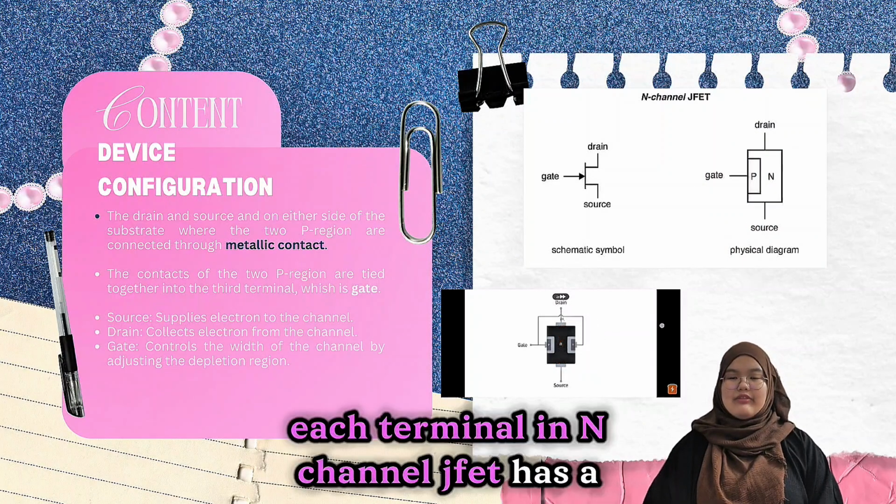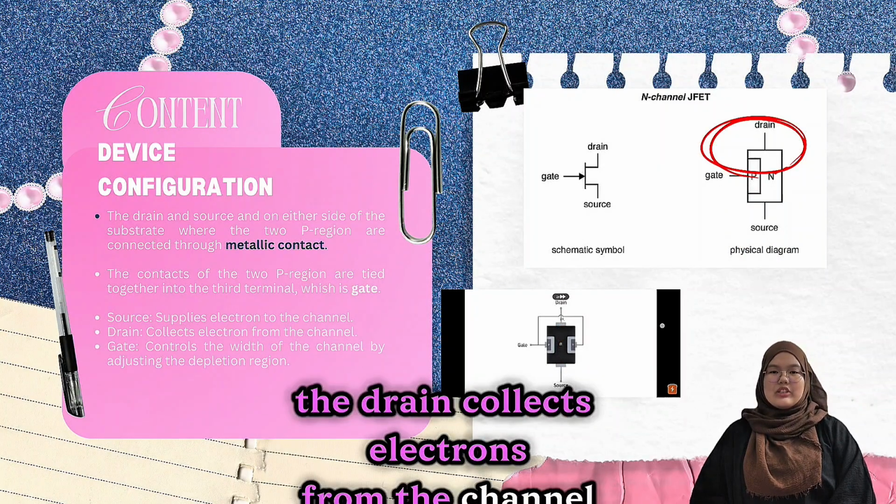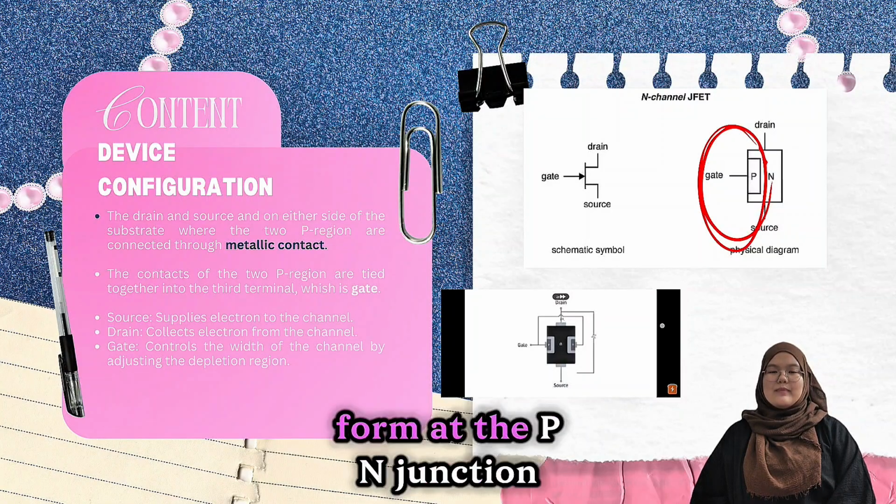Each terminal in an N-channel JFET has a specific function. The source supplies electrons into the N-type channel. The drain collects electrons from the channel after they travel through it. The gate controls the width of the channel by adjusting the depletion region formed at the PN junction.